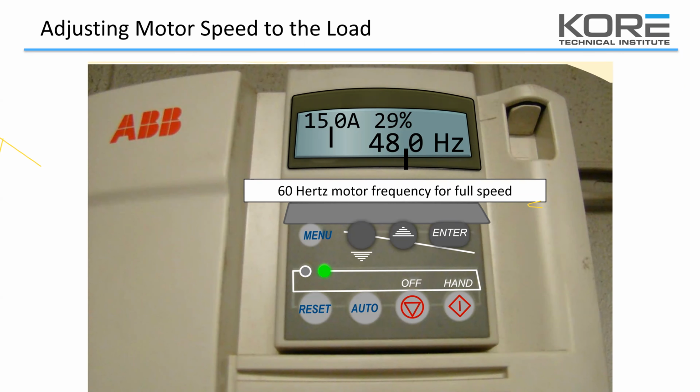There are several applications, like if you guys have ever worked on the Bitzer Speeds, mostly you'll see in Costco, the Bitzer Speeds run all the way up to 87 hertz. So they're spinning pretty fast. It's a smaller pump, smaller compressor that moves a pretty good amount of gas through it with a small footprint. And then it'll run all the way down to, I think, 38 hertz or 40 hertz. So on full speed, it's spinning pretty fast.